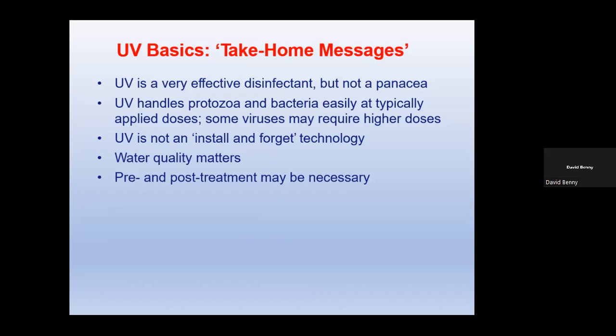These things require some maintenance on a routine basis, either at a 3-month or 6-month level, because UV systems such as these do not come with automatic wipers, and you have to frequently clean the tube to make it effective.